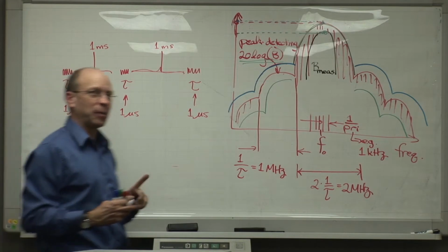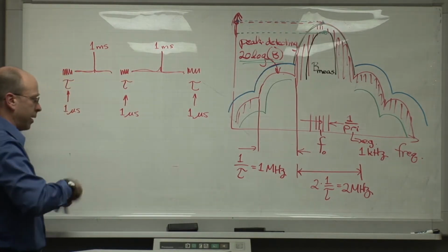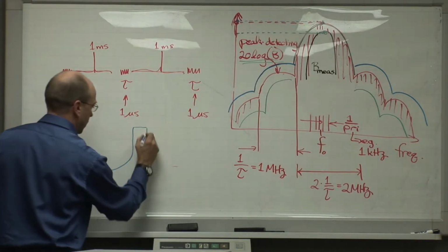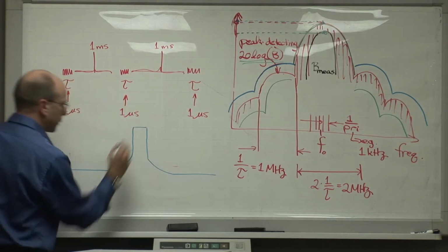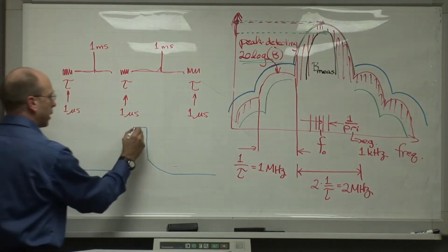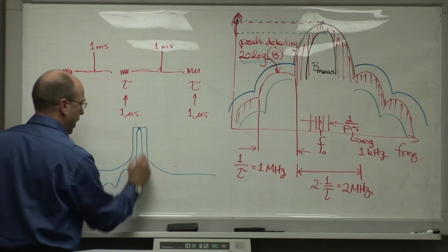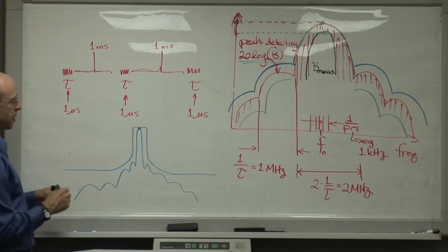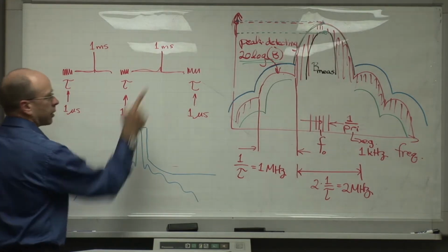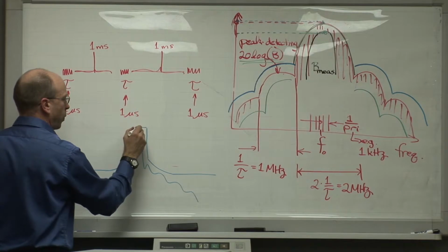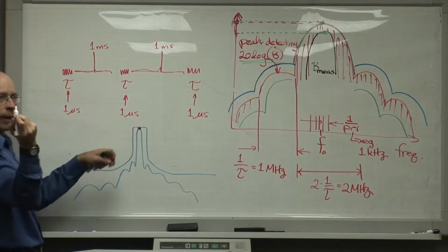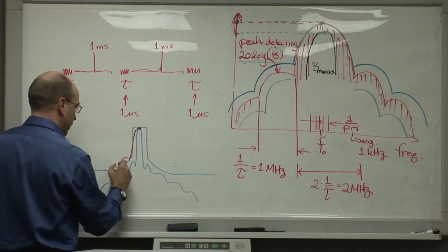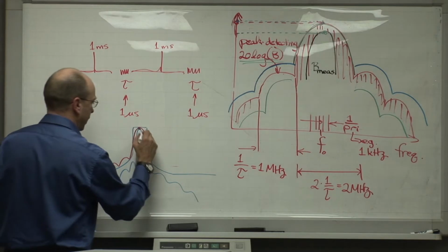Okay, wait a minute, there's a problem. We said that we wanted the spectrum emissions to fit underneath a mask that looks like this. And we said that we were going to measure power here, and we're going to get the spectrum out here under the mask like this. We want to see if it matches it. And what I've just done was to put together a scenario where if we measure in some bandwidth, we get the same power here in the second red bandwidth as we had in our first blue bandwidth, but where the spectrum emissions out here run out like that.